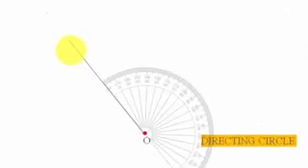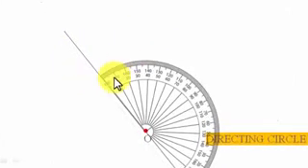Alright, so we've made a point. Let's say the name of this point is O, and this is what you call the center of the directing circle. The entire directing circle is not to be made, rather a sector that is 102.8 degrees is going to be made. Okay, so this line that I have drawn, it represents the radius of the directing circle having a magnitude of 87.5. Fine. So let us have a protractor over here. Okay, now the angle subtended over here is going to be 102.8.